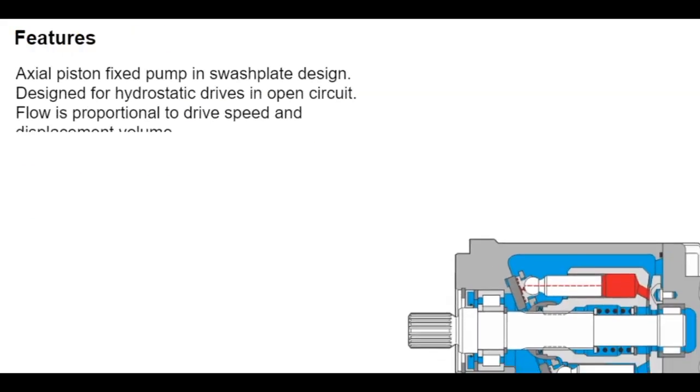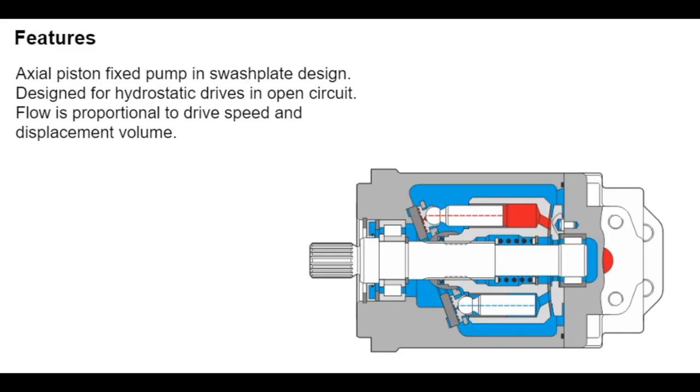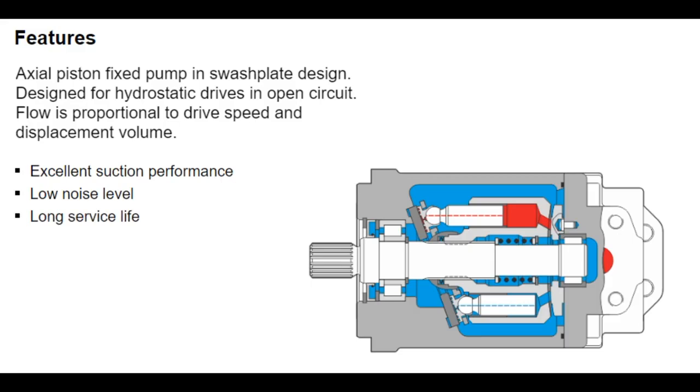The fixed pump A4FO in swash plate design is specially designed for hydrostatic drives in open circuit. The fixed swivel angle makes the flow proportional to the drive speed and the displacement volume. The displacement volume can only be increased by increasing the drive speed. The large cross-section of the suction port ensures good suction performance with low noise. The hydrostatically mounted slipper pads also extend expected service life. A special range with through drives on the port plate makes various pump combinations possible.